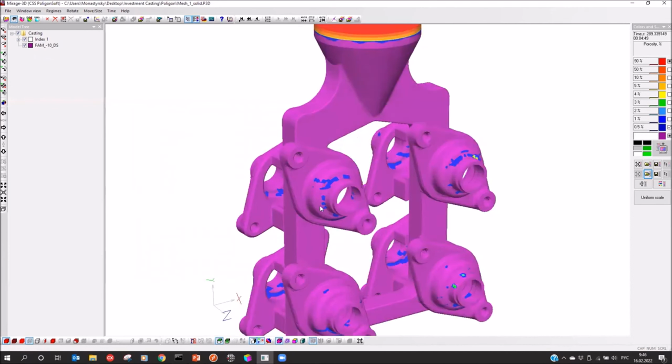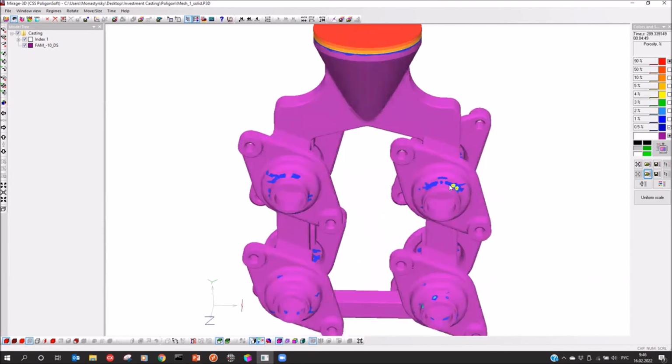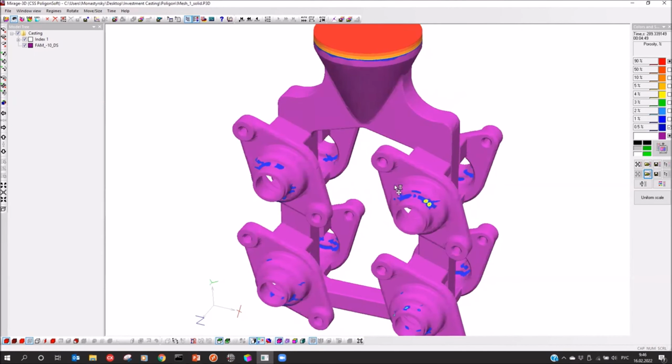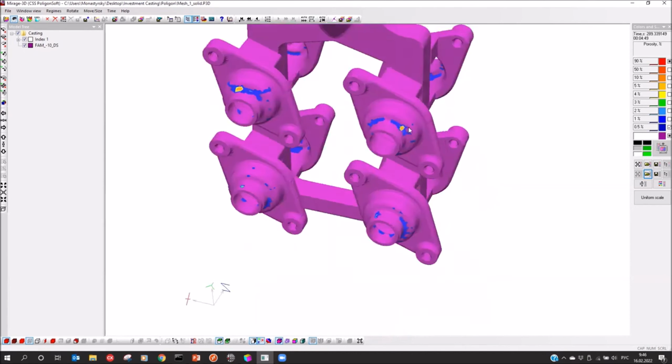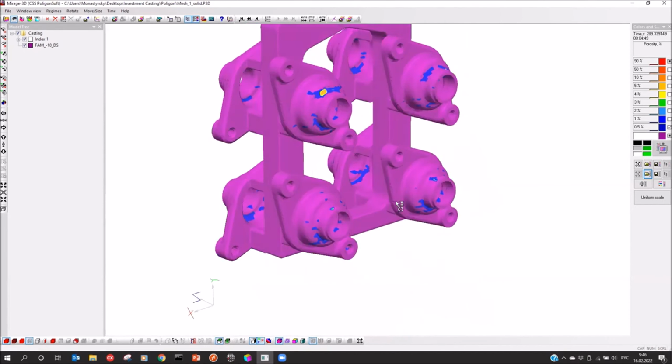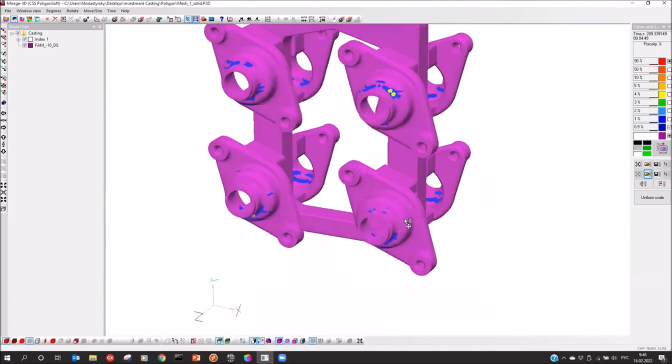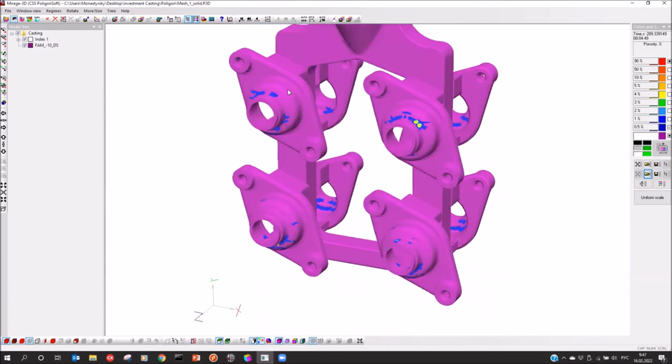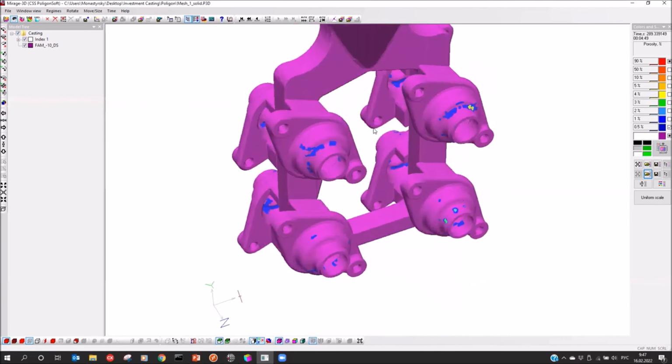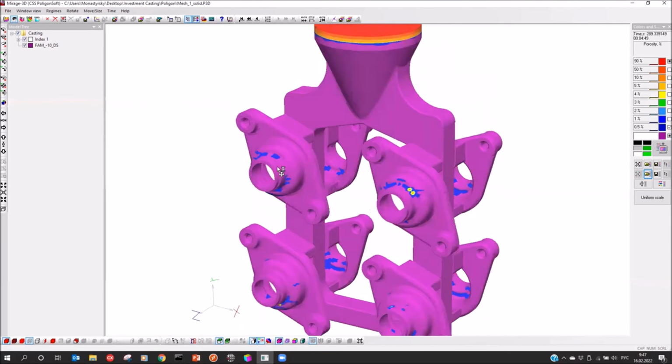I think we see it because the cooling rate is too high here, and we see some small cavities here and here. Yes, in every casting part we see this. And as for this microporosity, if casting parts are controlled by X-ray, it will be a problem. If not, I don't know, maybe it's not a problem. It's hard to say the first time.